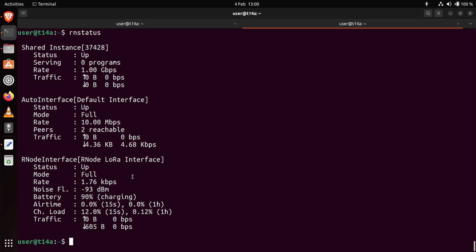So that's how to flash the firmware to an RNode and then configure it, and then to put the data into the config file that's needed to communicate with it, and for it to communicate then over the radio interface. So that's all I want to show you at the moment. This then is ready to be used, this RNSD. It's ready to be called by other programs that need it, or just to run on its own for routing traffic through the Reticulum network.